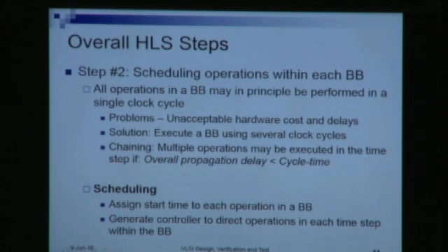Now, what we have to do is schedule the operations within a basic block. So then what is a basic block? We will see that a basic block has no control or loops inside it. Therefore, it only contains a set of paths for data to flow. So data will go into the beginning of this basic block. Input data will enter, and these input data will go through a series of transformations because of the combinational operations.